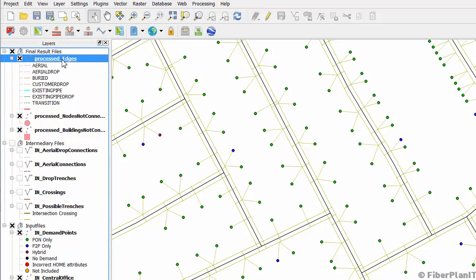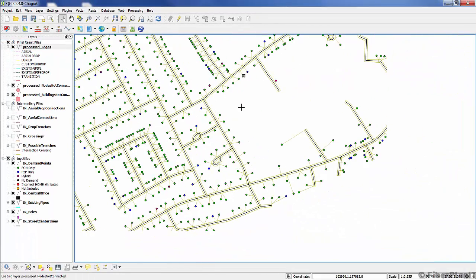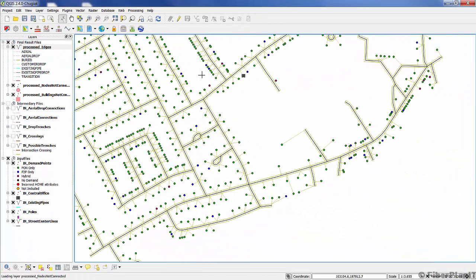This mapping will be used for any subsequent calculations. So it's very important that when you make any changes to the input data of your design, that you finalize these changes by processing your area in order to update the mapping file as well. This concludes the processing steps for a regular buried area.